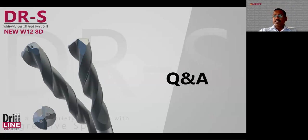Okay, thanks again, Mr. Dimitri. So far, we have never tested 50 HRC superalloy materials. The highest we test is Inconel below 40 HRC, and also some titanium materials. Is it possible to drill? Yes, definitely it is possible to drill under certain conditions. You need to apply low cutting speed and low cutting parameters. Definitely the drill will be able to perform.